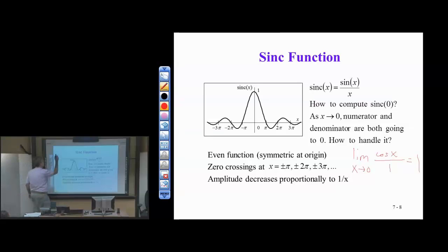The other version of sinc, where are the 0 crossings? Call it the other version. That's the MATLAB version. What is that one? It doesn't affect the value at 0, which is still 1, and the 0 crossings are now going to occur at what values? Yeah, plus or minus 1, plus or minus 2.